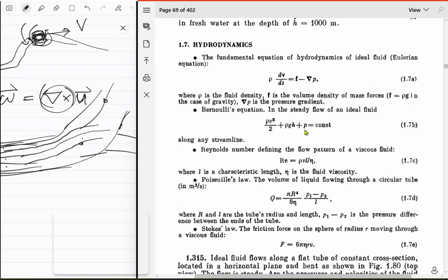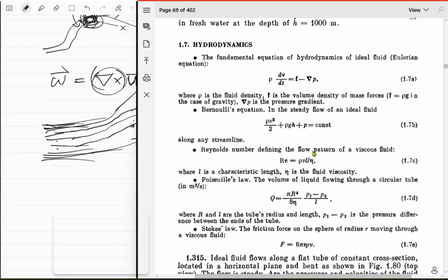And that is something that we'll be using a lot, because everywhere that we'll be calculating anything, the first assumption will of course be that viscosity is zero, right? I mean, wherever we'll be calculating with Bernoulli's equation. Because if there's viscosity, then you can't apply energy conservation anymore. So of course we're assuming viscosity to be zero everywhere, which means we will just have the water flowing from a tube initially with all these streamlines having the same constant in any case, right?